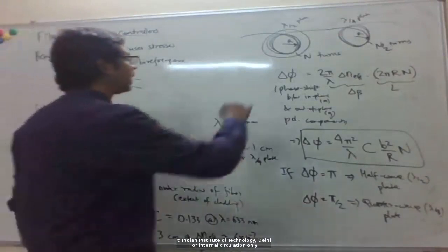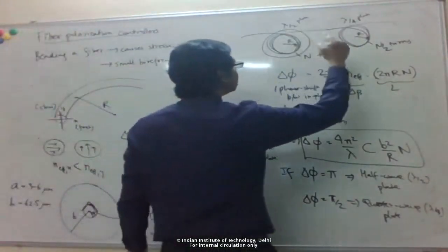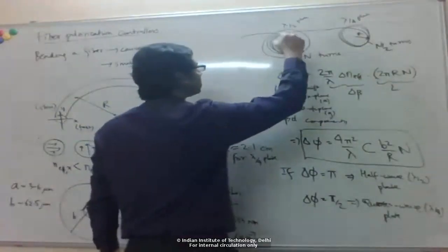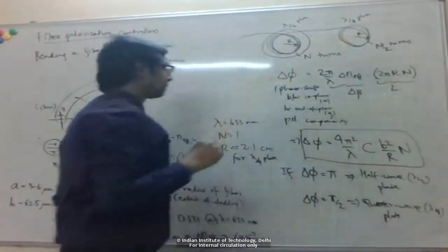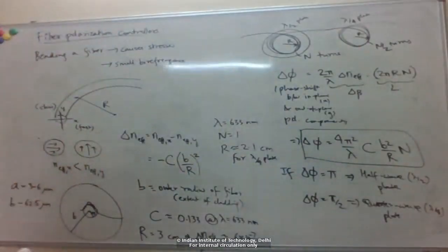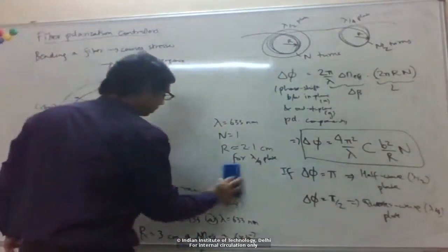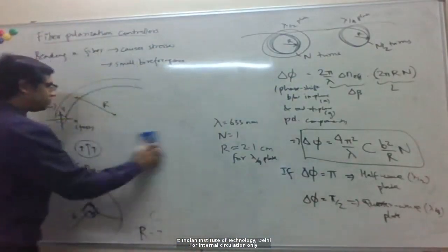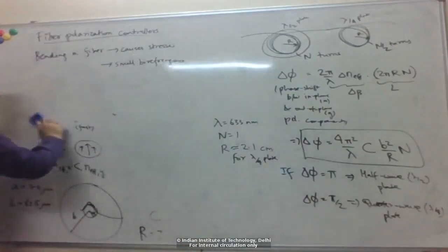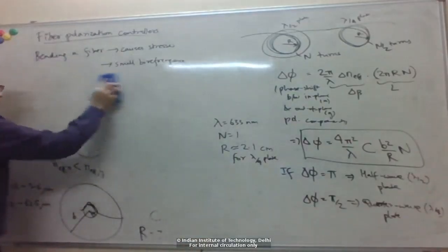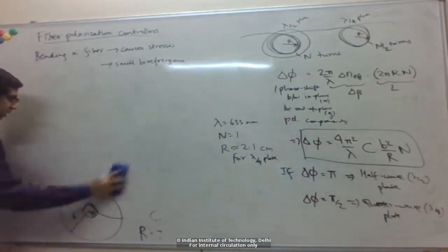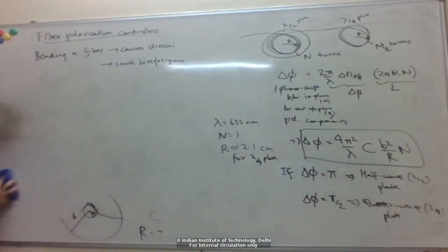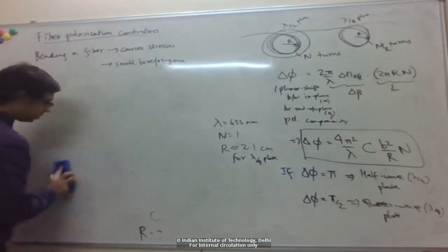And so we can build a device which has these quarter and half wave plates in succession, and that can be used to compensate or recover the polarization to what you want. Again, from free space optics, it is known that if you have any arbitrary elliptical polarization, and you want to convert that into some other arbitrary polarization...